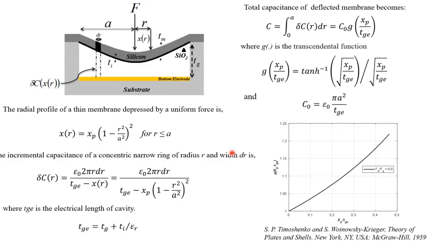So you can think of a CMUT built on a thin substrate as a bilateral CMUT. That is, it's not only the silicon that is moving, but there is a substrate which is not very easily moved, because it's a solid and it's not flexural like silicon. So it does have a compliance capacitance, just like silicon over here in the front plate.